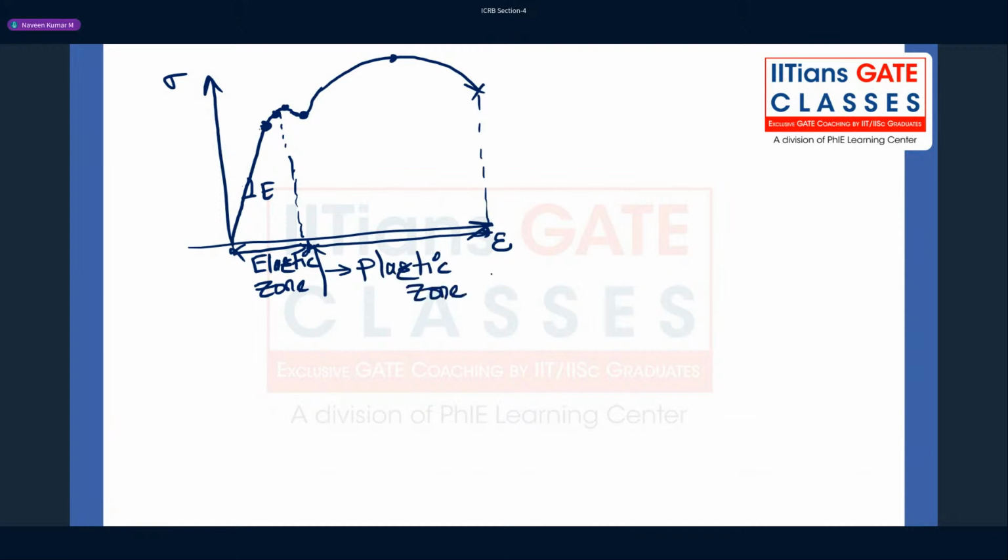Okay. So here, you see that after the upper yield point it is going into the plastic zone, and surprisingly, as the deformation is increasing, the stress is increasing very highly. Stress is nothing but the resisting force per unit area. So the resisting force is being increased. As you keep on increasing deformation, pushing or pulling, whatever it is, the resisting force keeps on increasing with the appreciable amount of strain that is happening there.